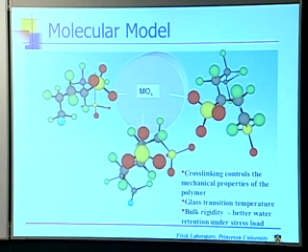So what's that going to do for you? What are we going to predict for that? Well, the first thing is one would predict that we're going to cut down on polymer mobility if we do this sort of thing. So we should change the mechanical properties of the polymer. Okay, make it a more rigid structure than if we were not doing this. Second of all, any phase transitions, and there happens to be a glassy phase transition in Nafion, we would expect would change in temperature, because again, this is a more rigid structure, and to do a phase transition, we're going to have to get these polymers to move around. They have to change positions, and it's going to be harder to do that.